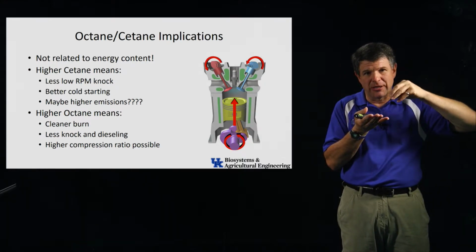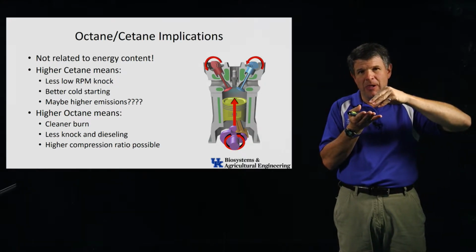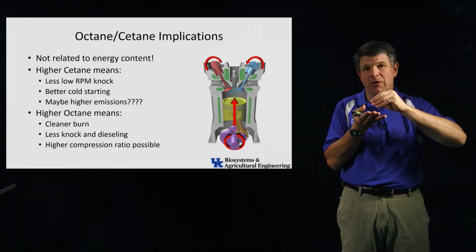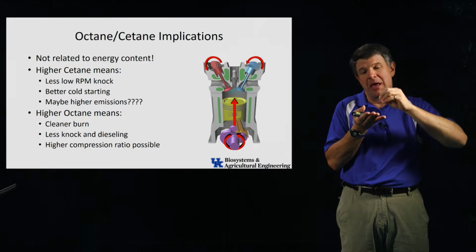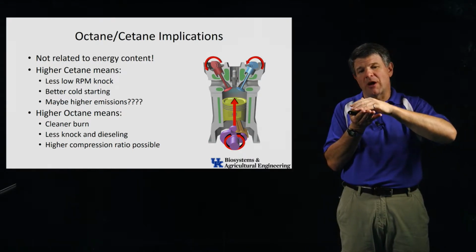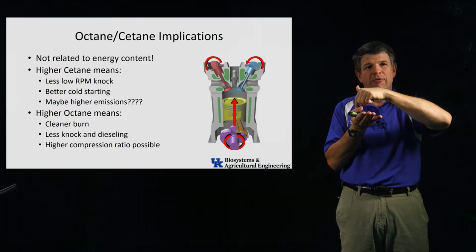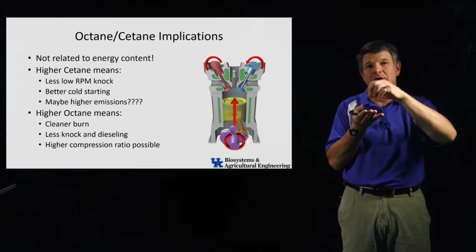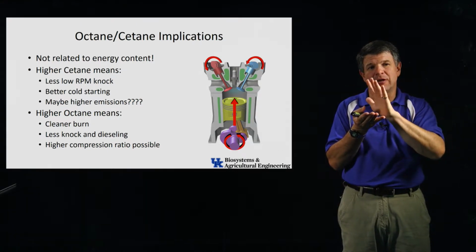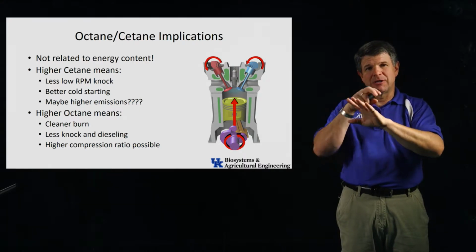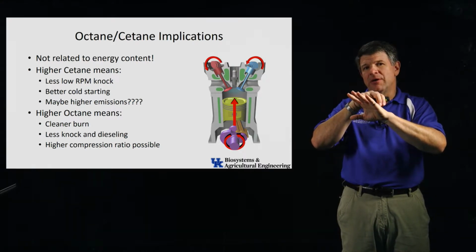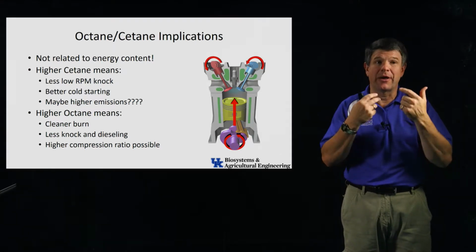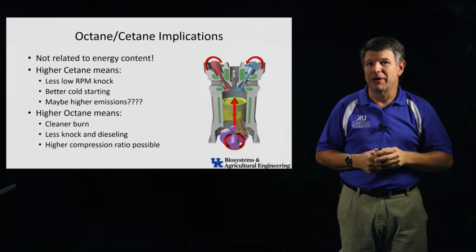So if I inject that fuel, it comes out of the injector, and it's a real low auto ignition pressure, it's going to start to burn right away. And what's going to happen is it may burn before it gets distributed all the way through the cylinder and gets mixed with all of the oxygen molecules that are in there. So I might get this burning front that goes out through the piston, blocks some of the fuel that's coming in behind it. I get incomplete combustion, and so I may end up with actually more emissions coming out of the engine.